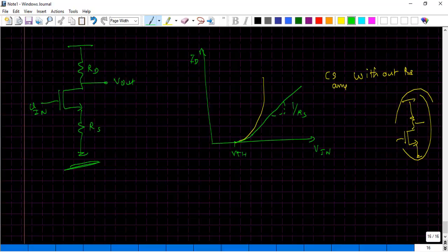As you know, once the value of V keeps on increasing, the potential across this would almost stay constant, and whatever I increase beyond a particular value would actually fall only across our Rs. The more the V that I apply, only a small change happens across the gate to source, but there is a huge change across the resistance Rs. And the current that flows, the ID current, could be redefined as Vs by Rs.